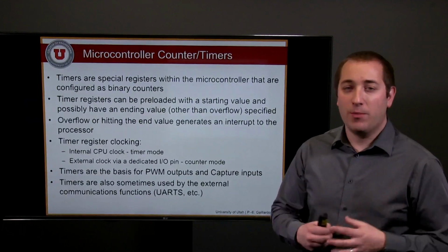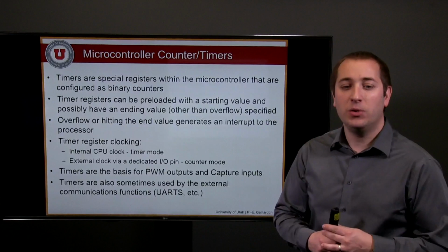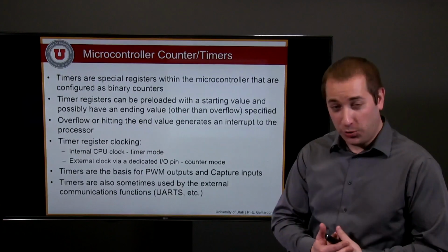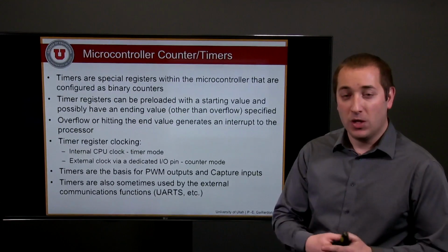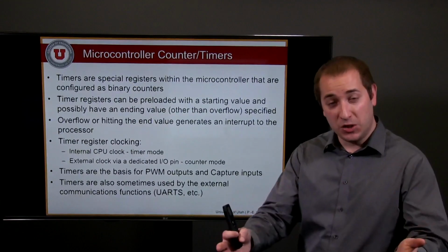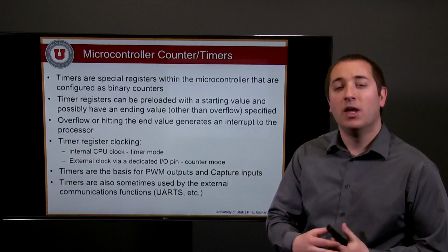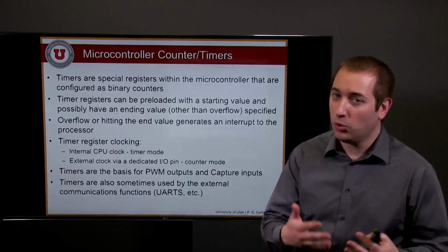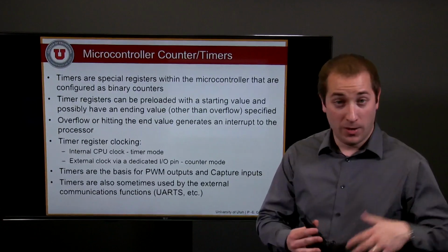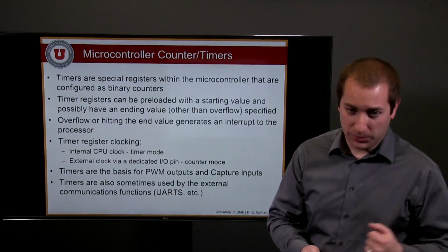So what are timers? Timers are actually special registers within the microcontroller that are configured as binary counters. So those are registers you can read and write into, but at the same time, they are incremented, or decremented as a matter of fact, thanks to an external clock resource.